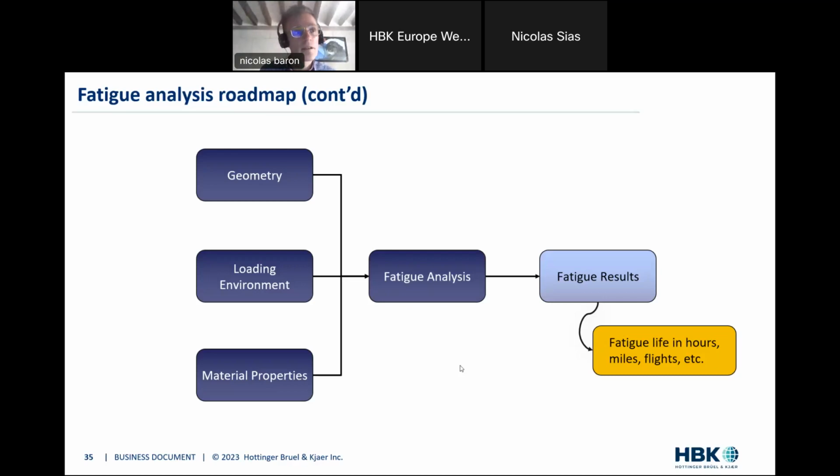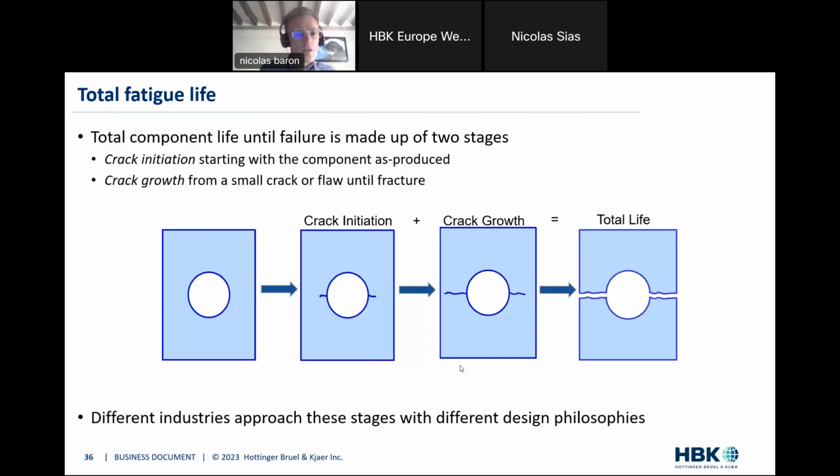And I think typically when designers in the car industry design the car or components of the car, it's really designed for withstanding a given number of kilometers, typically 250 or 300,000 kilometers, or 15 years. Well, this is how you would express warranty values, and fatigue is expressed in this same unit. So fatigue life, two stages.